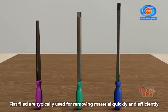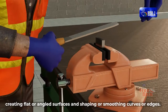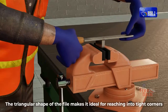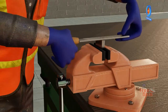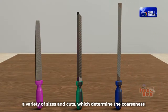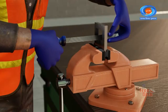Flat files are typically used for removing material quickly and efficiently, creating flat or angled surfaces, and shaping or smoothing curves or edges. The triangular shape of the file makes it ideal for reaching into tight corners and removing material from hard-to-reach areas. Triangle files are available in a variety of sizes and cuts, which determine the coarseness of the teeth on the file.